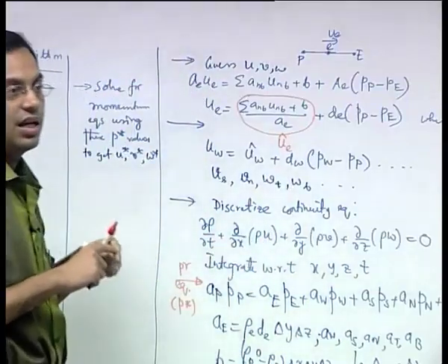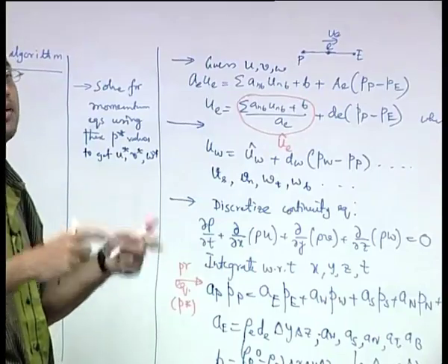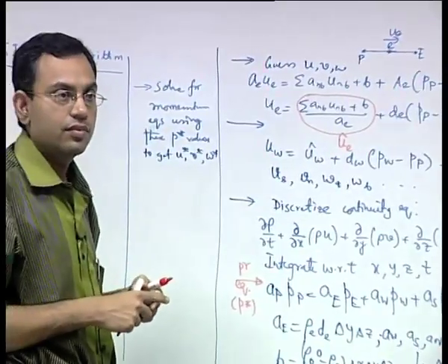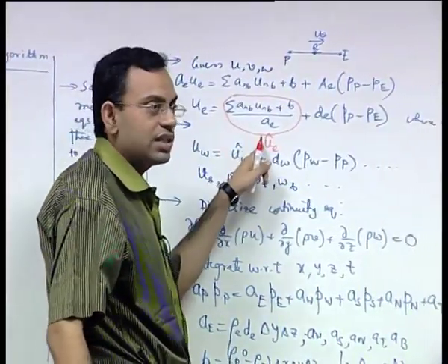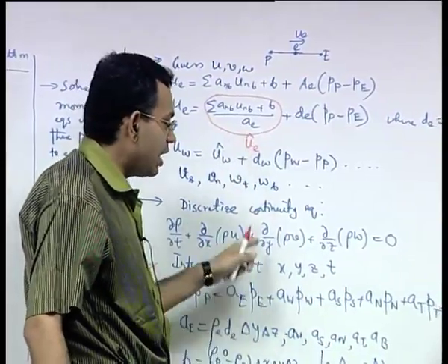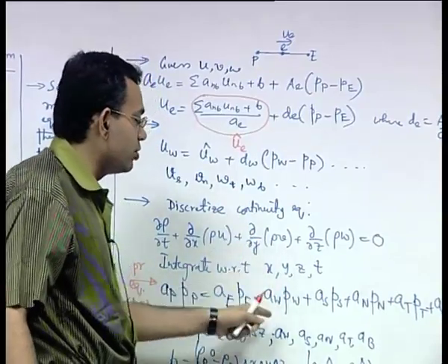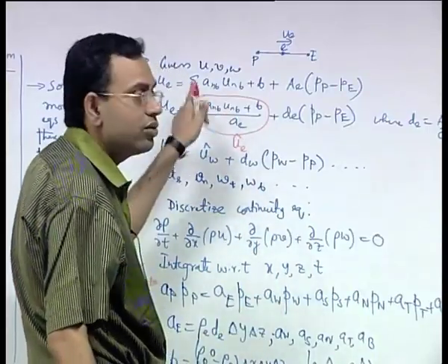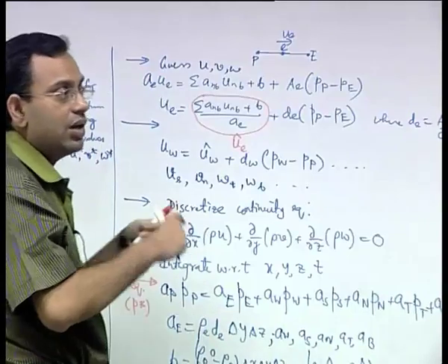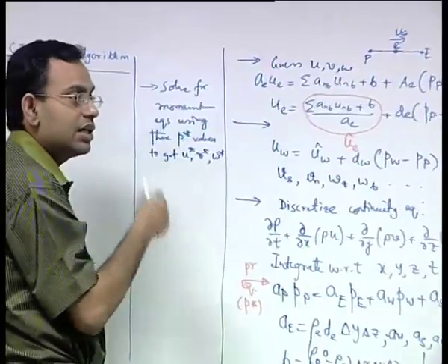That is the effect of neighboring velocity corrections on the velocity correction itself and on the pressure correction itself. These effects were neglected. Here there is no such neglecting, so the pressure equation is expected to give a reasonably accurate value of pressure depending on how good your guess on velocity is, but the velocity anyway will be updated, it will be updated based on the pressure correction equation.